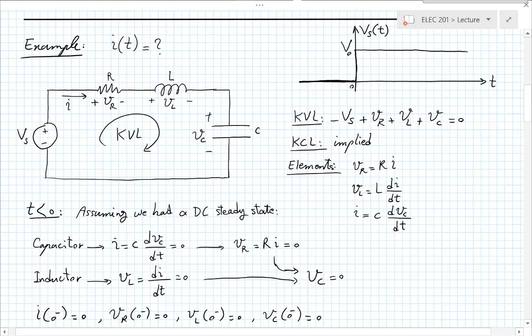And because they're both elements that just store whatever energy they take from the circuit, they can give it back to the other element and go back and forth. But once you put the resistor in, it will start consuming some of that energy and turning it into heat, which will actually eventually leave the circuit, radiate out of the circuit, conduct out of the circuit. And so as these oscillations are happening back and forth between the capacitor and the inductor, every time a little bit of the energy is wasted in the resistor. And that's why the oscillation will gradually die out.